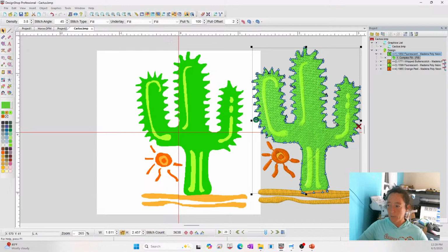Rachel typed in she's got a tip: always press the e-stop and actually double check the points. Not a bad idea. If you do it mid alignment where you're going to point 1 then point 2, it is timed, so be quick about it. So if you're going to 1 before you hit laser left, you drop it and check it. Laser left, that's when the time starts, right? So laser left, you move to point 2. If you e-stop and drop it, be quick about it. Don't sit there and dilly-dally because you need to do laser whatever and then laser bullseye pretty quick after that.